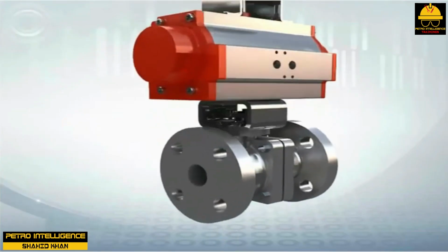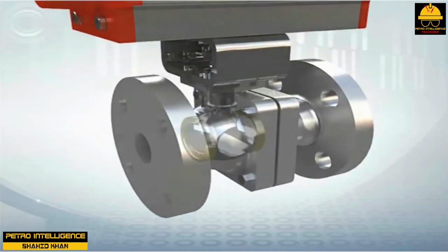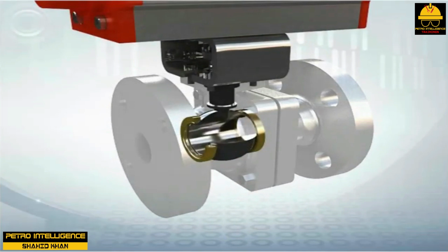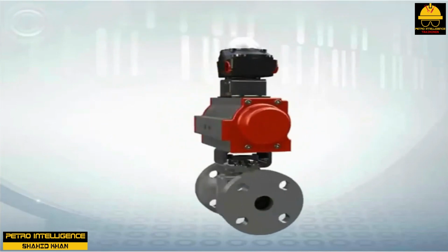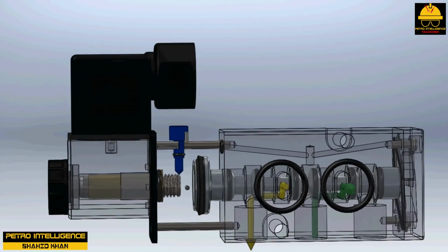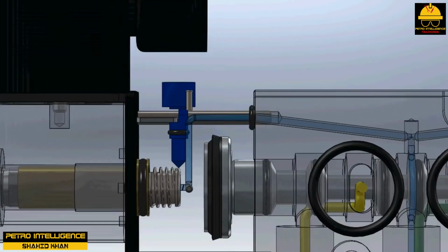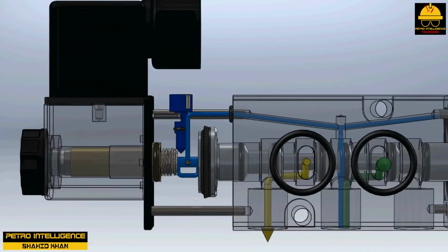Electrically operated actuators convert electricity to mechanical energy. There are two types: solenoid valve and motor-driven actuator. Solenoid valves are designed for on-off service. The internal structure of a solenoid resembles a globe valve. The disc rests in the seat, stopping flow. The stem is attached to a metal core or armature that is held in place by a spring.